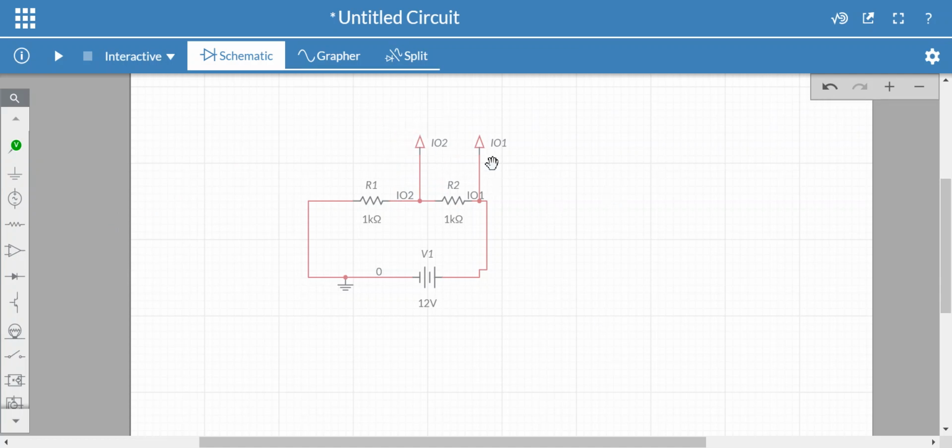I'm just putting it down and then dragging it to make it longer. Okay, so now that shows that I've got 2 wires across the resistor R2, but I don't know where they go, and it doesn't matter where they go. That's just for my schematic diagram, just to show I'm going to use those 2 wires as my power supply now. So that was a discovery I made in Multisim, how to make wires go to nowhere, essentially. Okay, what else?